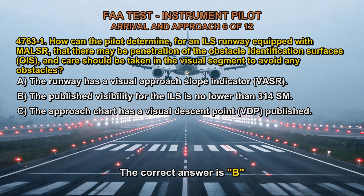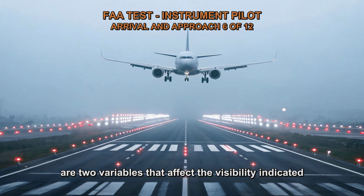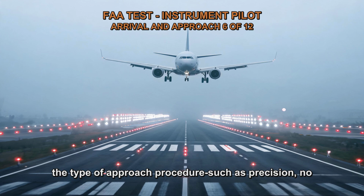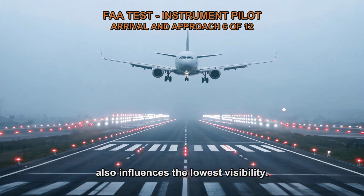The correct answer is B. The height above landing for straight-in approaches or the height above airport elevation for circling approaches are two variables that affect the visibility indicated on an approach chart. The coverage of the approach light system and the type of approach procedure such as precision, non-precision, circling, or straight-in are additional criteria. The penetration of the 34:1 and 20:1 surfaces also influences the lowest visibility.